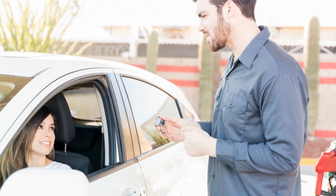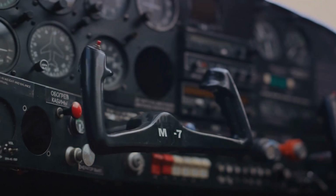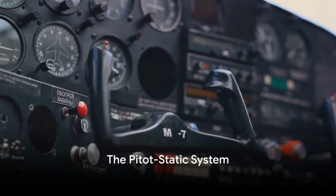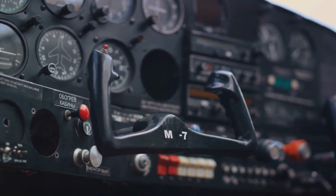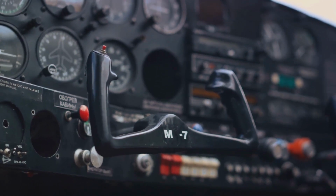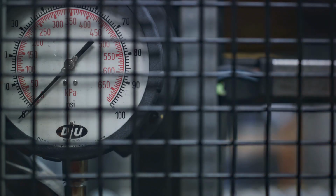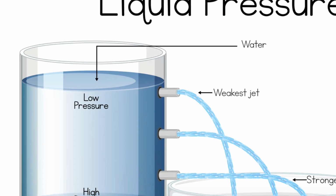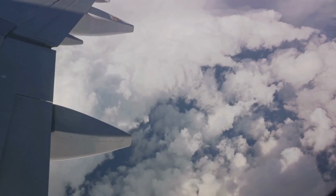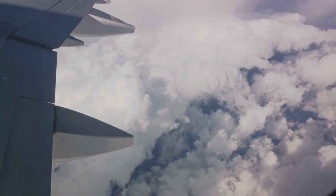So, the static and dynamic pressures are fundamental components of an aircraft's pressure instruments. Now let's delve deeper into the pitot-static system, a crucial part of pressure instruments. This ingenious system comprises two elements, the static port and the pitot tube. The static port measures the static pressure, which is the atmospheric pressure at the aircraft's current altitude, exerted equally in all directions. This pressure is a result of the weight of air molecules pressing down from above, and it doesn't involve any relative movement of the air.